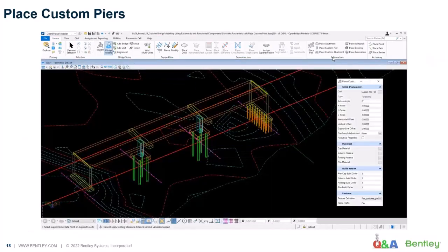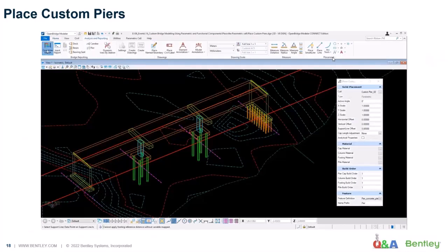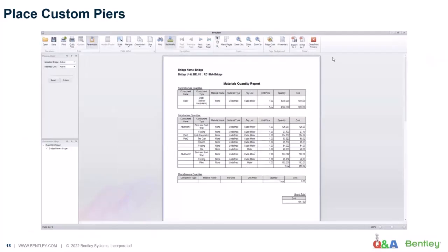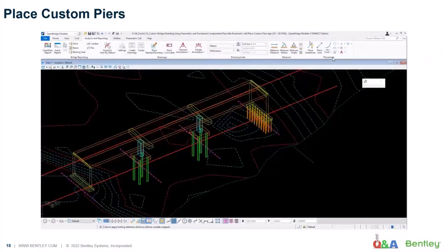Now, if you need to modify it, that's where we go into the next step, in which we say, well, this is placed, what about changing dimensions, right? But then I also apply the tags. Remember this, the cell will have the tag. So my quantities are computed because I assigned the proper tags to it, right? We don't just sell a parametric cell, but if I apply the proper tags, the quantities should already be there, basically computing the solid model that you assign.